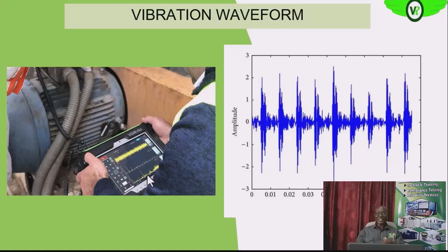If there is a dent in the inner race, there is a particular frequency at which you will see such a problem. If there is a dent in the outer race, there is also a particular frequency at which you see such a problem. If the bearing is cocked on the rotor or is loose on the rotor, all of this information you will see at different frequencies of the spectrum.